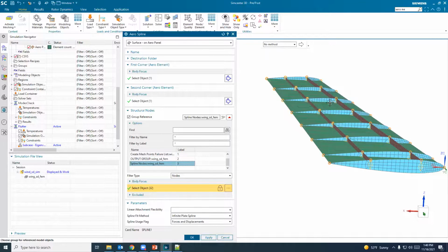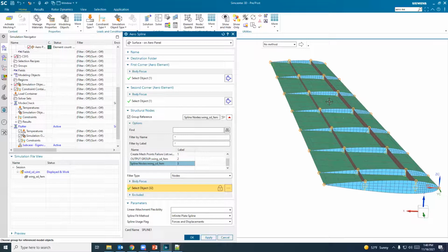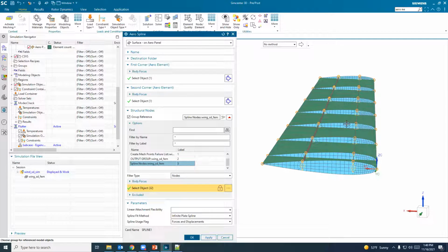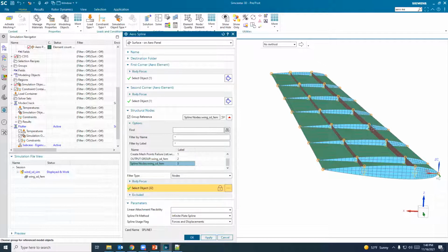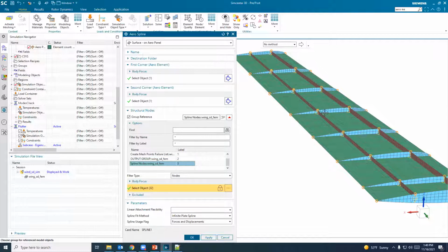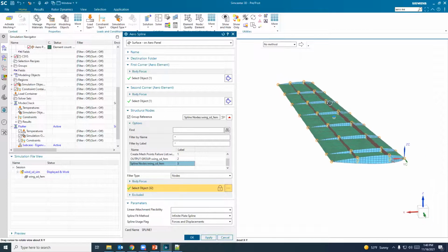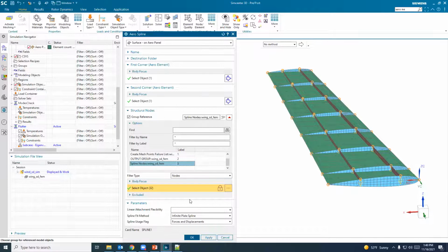And it's useful to pick points where there's some stiffness. We don't want to pick the middle of a panel that may encounter some type of panel response in our modes. It's better to pick stiffer points where you have maybe the intersection of the rib and skin, or intersection of spar and skin, or all three, to give a nice harder points, you might call them, to avoid any panel modes in the response, unless you're specifically wanting to include that for some reason.